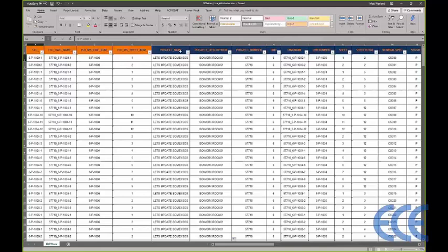So we open up the ISOs, you can get the data a couple different ways. A lot of companies are just using the AutoCAD data extraction tool, extract all the tags out, plop them across the top here. If you're working with an existing Excel line list, you can just append this row at the very top and hide it when you're finished so that your line list looks the same to the end product when you print it, but it will have this additional information in there.